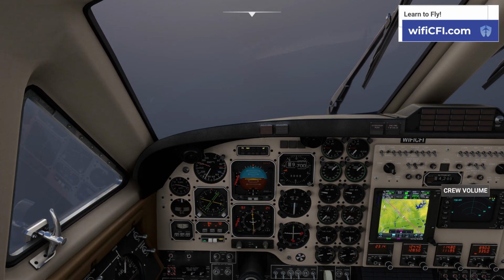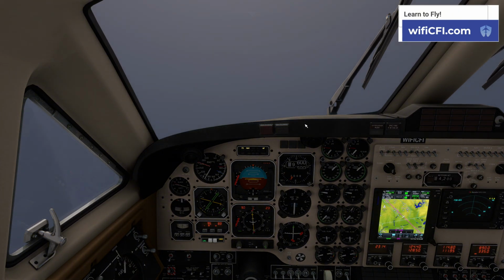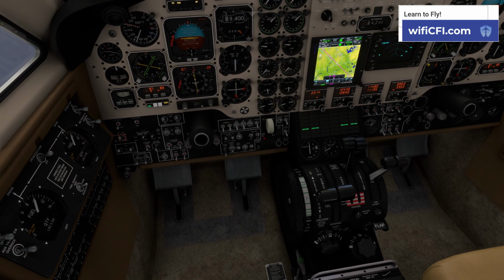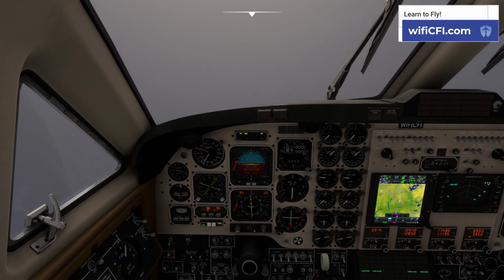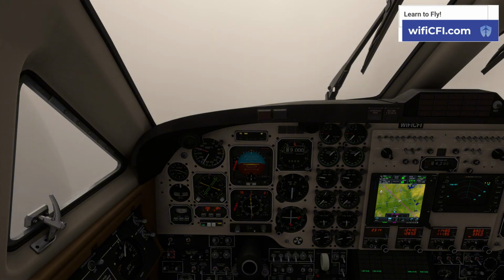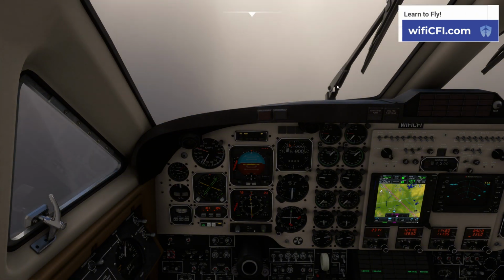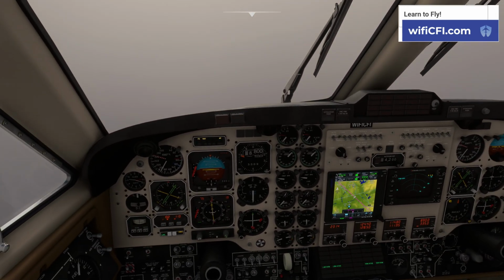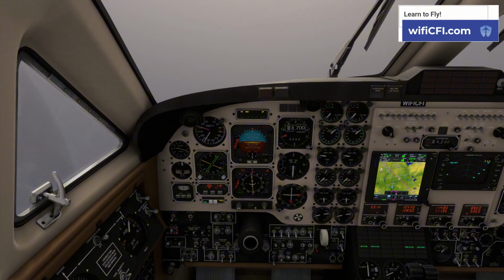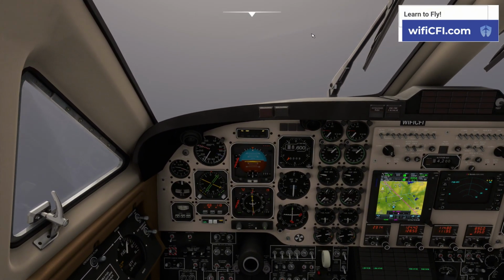About 10 miles to go. Altitude might be okay. Get down to that 4,200 in time. Pretty sure that's all of our approach, descent checklist. Yep. Approach reels and navigate set, altimeter set, auto feather checked and armed. We have that pressurization. Cabin sign, just going to tell everybody to sit down. There we go. Now we just fly, guys. We just fly.